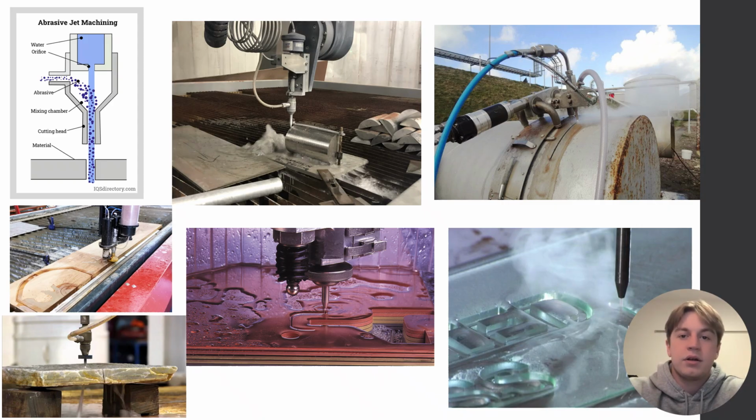And then in the center, you have stacked materials, which are an advantage that abrasive water jet cutting has. They can cut multiple materials stacked up on each other. And the top right is an example of a rotary mobile abrasive jet cutter that can cut round shapes and intricate molds, not just a flat sheet like regular saw cutting can only do.